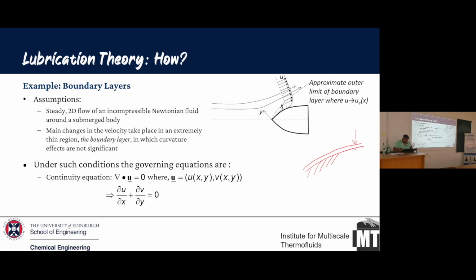And typically the boundary layer thickness is given by delta naught. Okay? It's an approximate. So this is how your boundary layer is in comparison to that. So one thing we quickly say is delta 0 by L, if L is the length scale of the wall, is much, much smaller than 1. Okay? So obviously if you consider this region, it's almost looking 2D. Yeah, boundary layers also have 3D features, but if you look at it from that perspective, they are essentially 2D. So because they are 2D, I can actually use a 2D equation here.